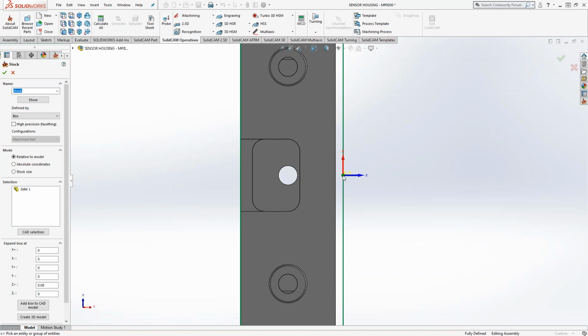Now, Jake, you're saying, wouldn't it be harder to indicate? Yes, it would be harder if you're using an edge finder and indicating it that way. But like I said, I would say the majority of the machines out there are taking advantage of the probe and probing up their part that way. And that's why you'll see a lot of us stay with top center, versus going off to the upper right-hand corner or upper left-hand corner.